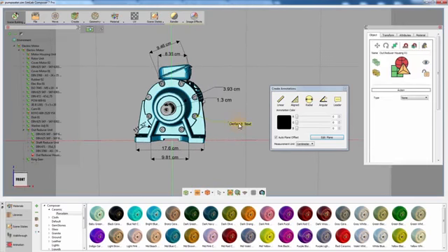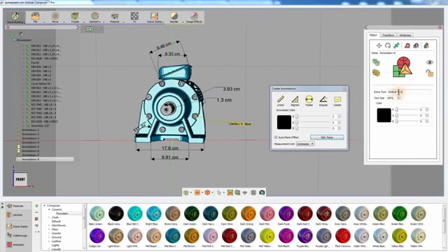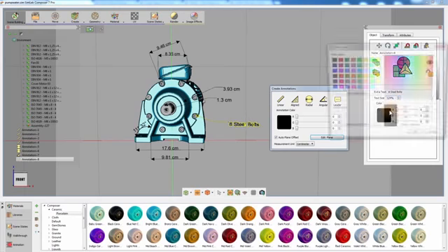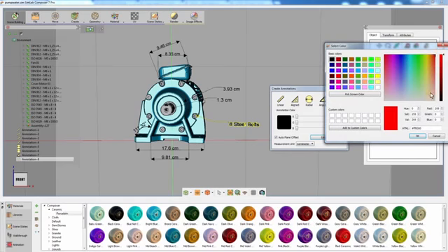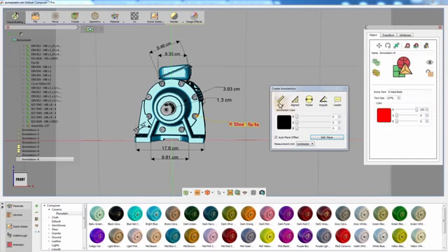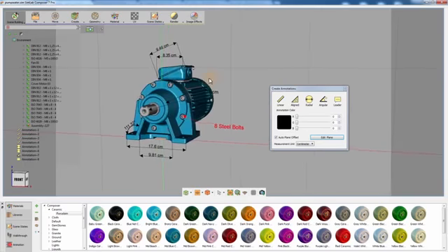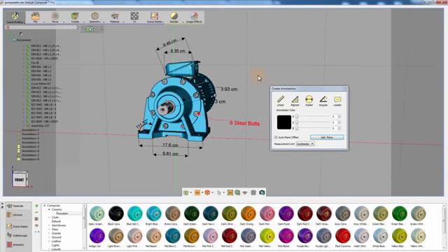Click on the newly created leader annotation and from the Attributes panel to the right, change its caption. You can also change the size of the annotation as well as the color. Those adjustable attributes apply to all types of annotations in SimLab Composer. The leader annotation is a great tool that allows you to add notes and identities to your design.